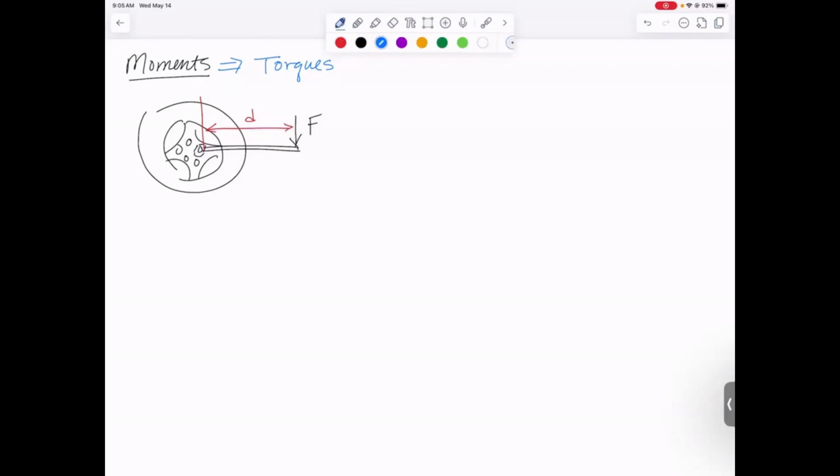How are we going to use this? Well, you guys remember Newton has some laws of motion. The one we've been using so far this semester is the force equilibrium equations. It's a simplification of Newton's laws of motion for when we have no acceleration. And that is definitely required for something to be in equilibrium. But then we also, in order for something to be in equilibrium, we have to require that all of the torques, but I want you to get used to using the word moments instead, all of the moments have also got to sum to 0.